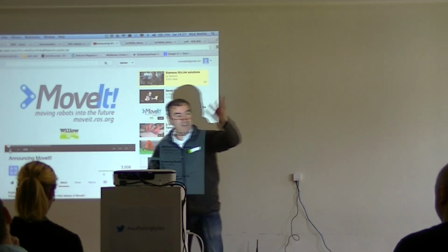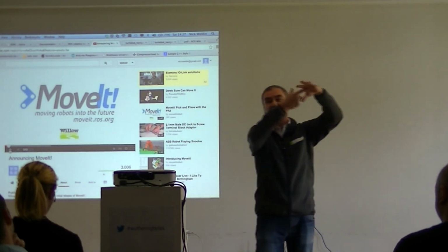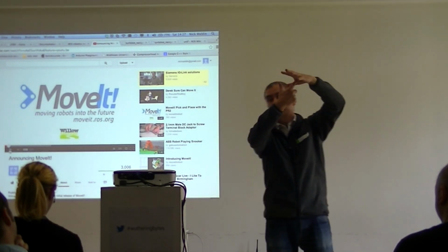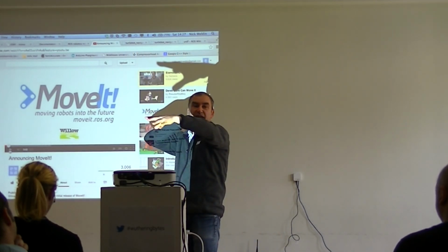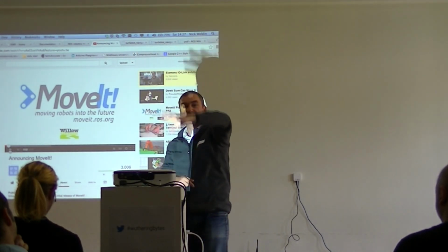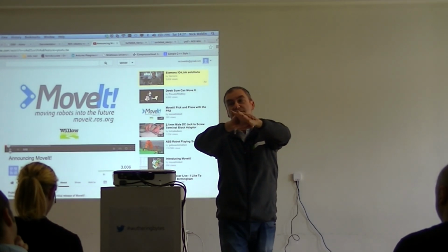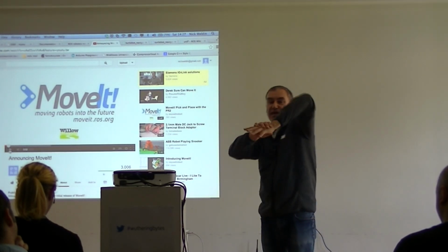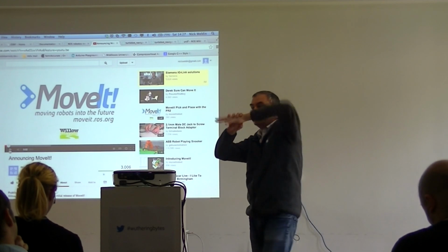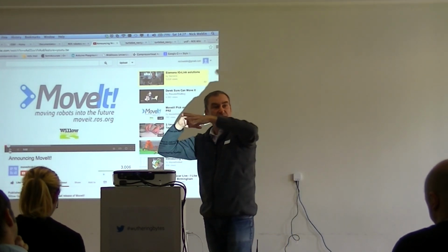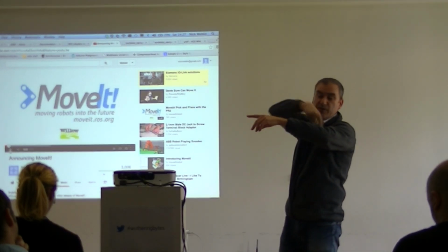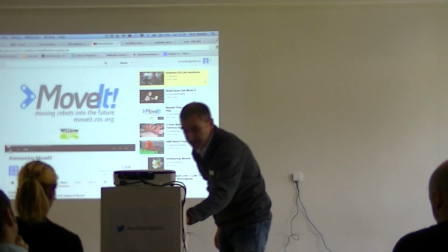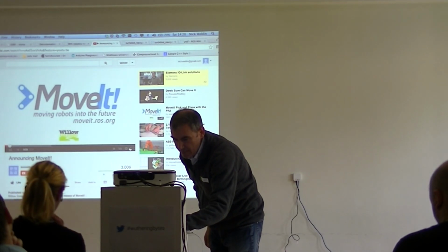So for an arm that moves around like this, what you're interested in is where the hand's going to go. So you want to specify where the hand is, and then you need to work out how all those joints need to move to get the hand to that position. And there may be multiple combinations of positions that would work to make that happen. So starting from those coordinates, going back, working that out is quite complicated.